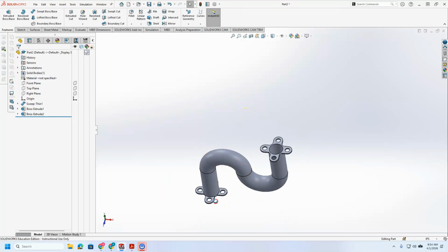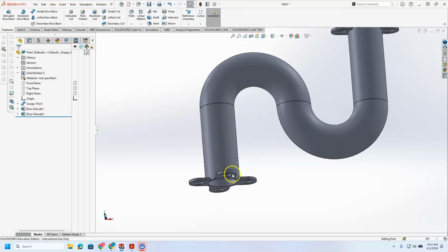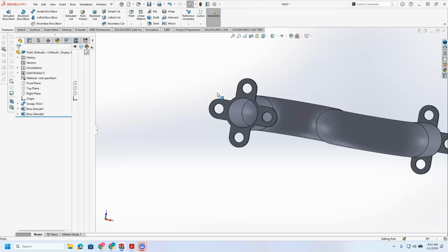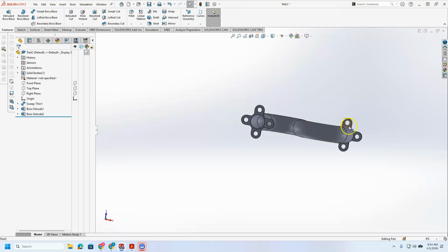Now you might be wondering, why didn't we just trim the slot command down here to make the same result? Unfortunately, you can't trim a slot entity. If you do, it loses all form and all relations, and you'd have to go back in and manually add all the verticals and all the tangents you need. It's much easier just to leave it whole and use selected contours. Those are the two ways to create those tabs, though.